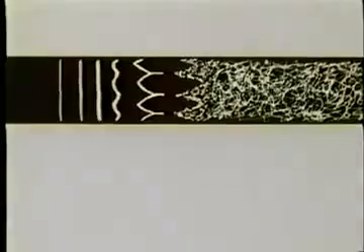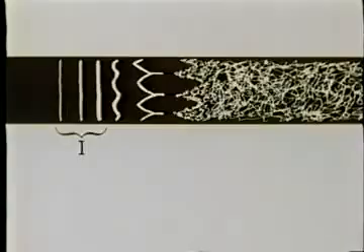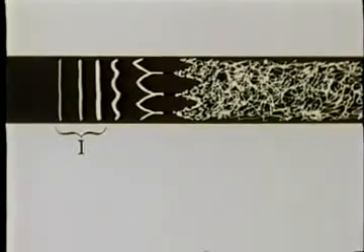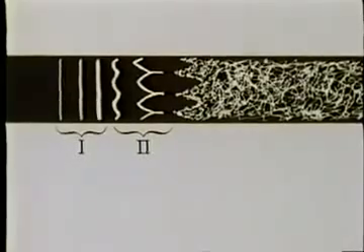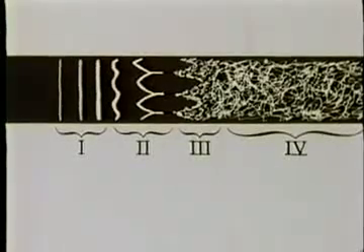Of nearly two-dimensional waves, the Tollmien-Schlichting waves, followed by the appearance and growth of three-dimensional disturbances associated with streamwise vorticity. Then turbulent spots can be seen. And finally, fully turbulent flow appears. Here, the exact position where growth of two-dimensional disturbances begins depends on random small-scale fluctuations in the flow, and therefore varies with time in a random way.